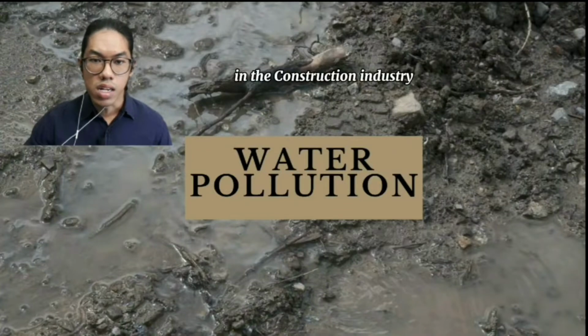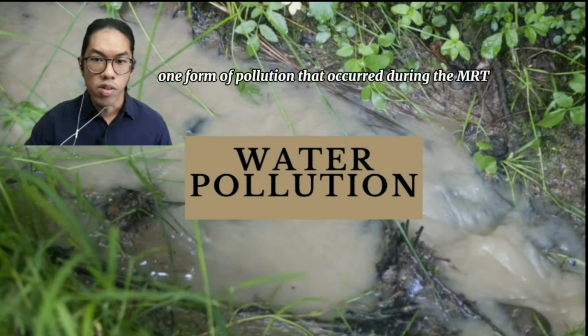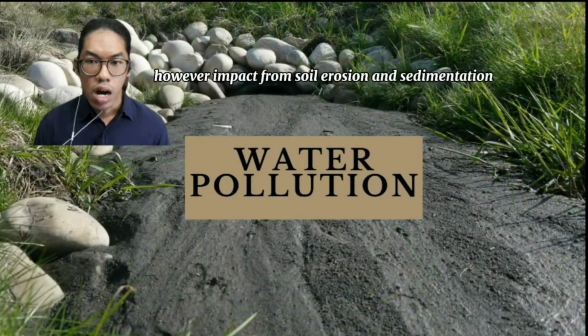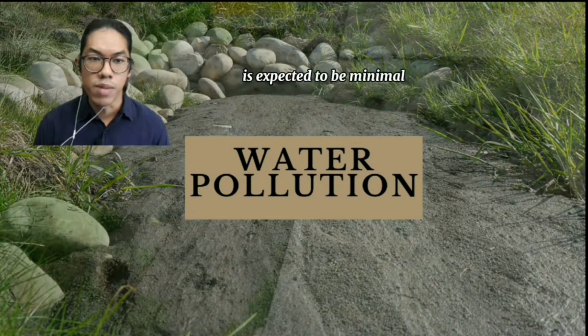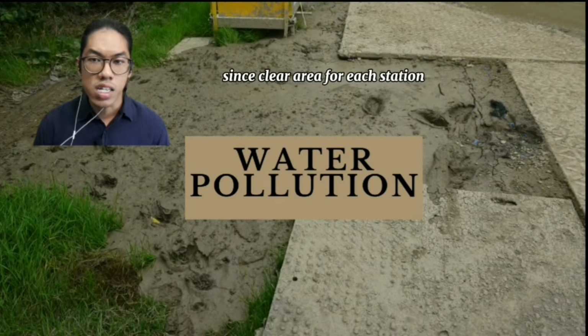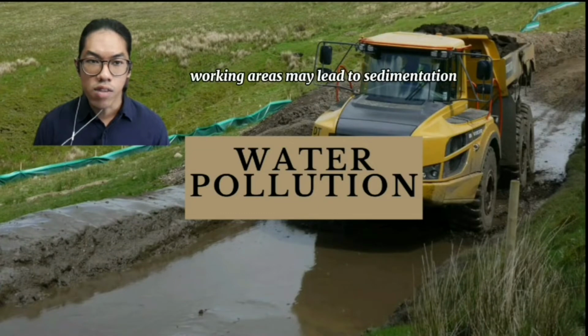In the construction industry, there's bound to be some form of pollution. One form of pollution that occurred during the MRT construction is water pollution. However, impact from soil erosion and sedimentation is expected to be minimal for elevated works, since the clear area for each station and piers is small. But the dewatering of the structure of working areas might lead to sedimentation.